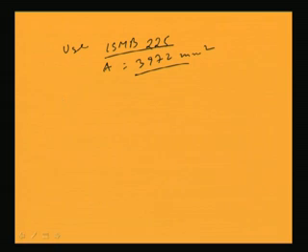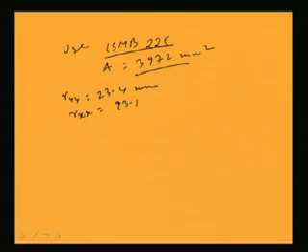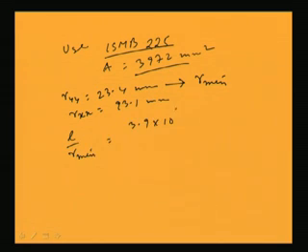From the structural handbook we will get other properties like RYY 23.4 millimeter, similarly RXX will be 93.1. So, RY will be the R minimum, right. L by R minimum I can find out. L is the effective length which we calculated as 3.9 meter by 23.4 which is RYY.